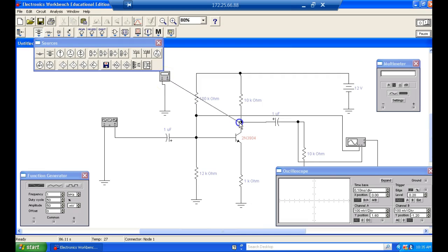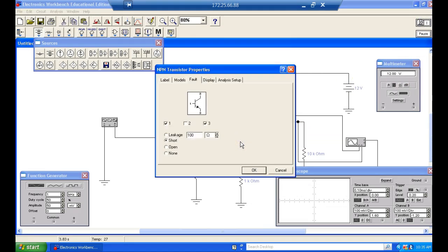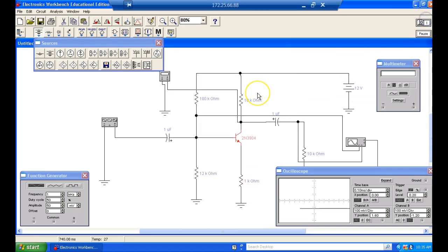If I measure right here, this is going to be way down. See there? Oh, I'm sorry, I don't want 1 to 3. I want 2 to 3. So this might be right. See? That voltage goes way down, right? But the telltale sign is I come over here and measure right there. And what does it measure? Yeah, it's going to measure exactly the same.